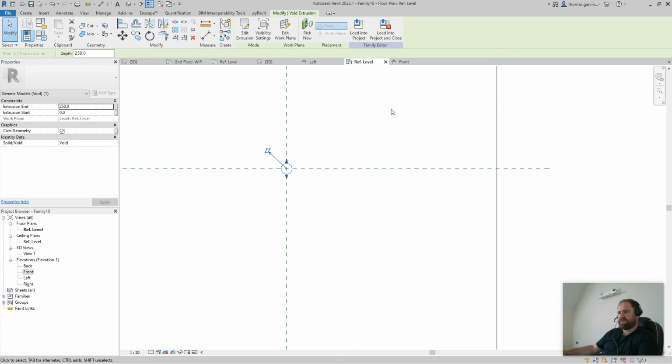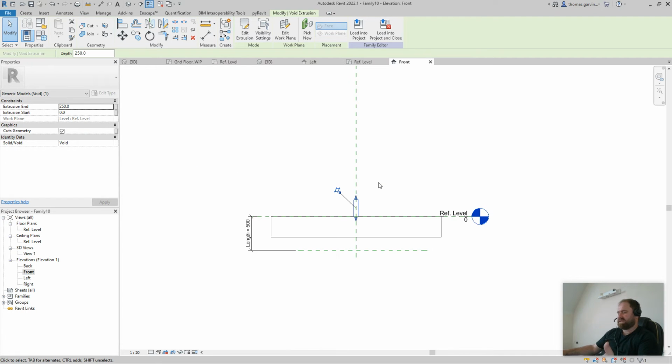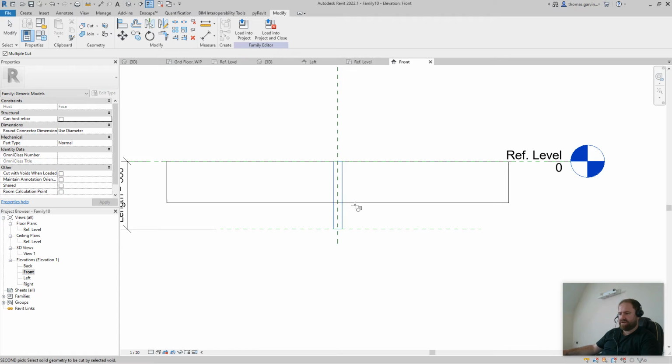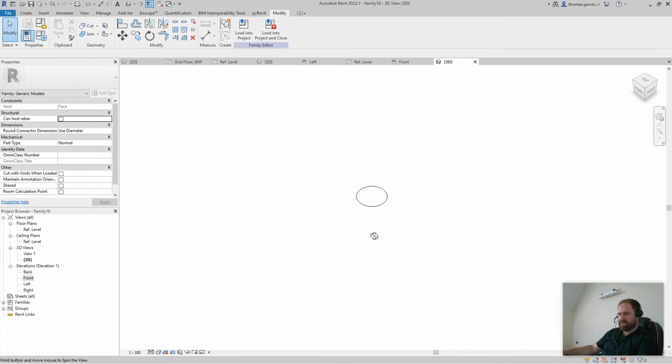And okay. Into the front or side, doesn't matter. Elevation is the point. And pull that little, you could use your align lock tool, but pull it down to the reference plane and it'll snap to it. Click your lock. Do the same with this guy up here. Lock. All right, or as I said, you could use the align lock as well. Then cut. Click your void. Select the face thing and cut.